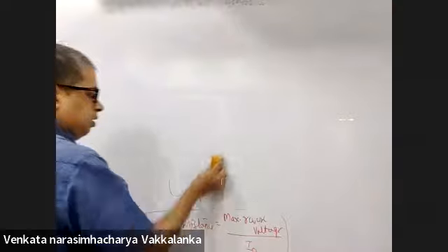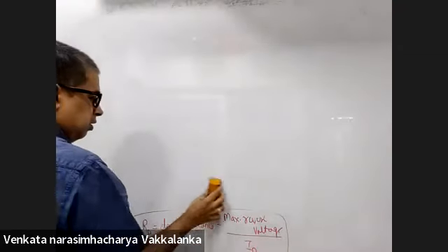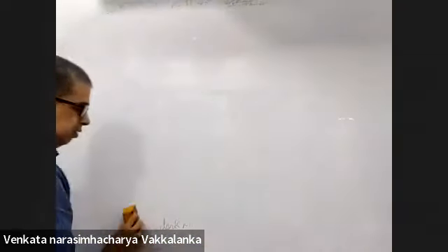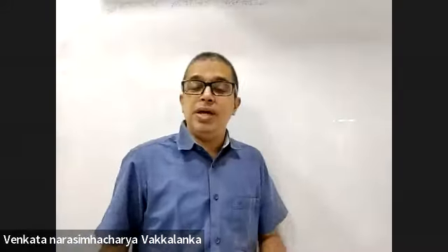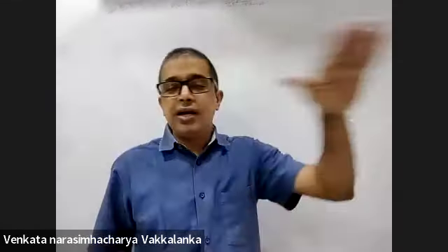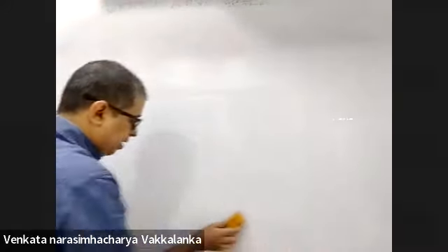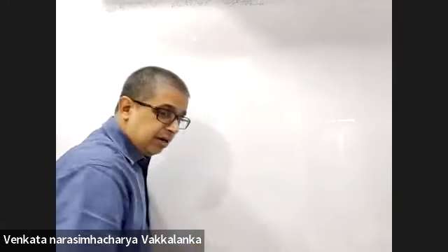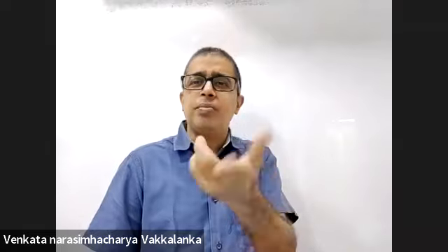So why had we reverse biased it? Even if it was forward biased, we would have got a similar graph of current versus intensity. But with a little bit of forward voltage, it will start conduction, and saturation will be reached very fast. Forward bias we don't want; even in the reverse bias we are having dark current. In forward bias, we'll have abnormally huge dark currents, even when light doesn't fall, with a little bit of 0.6 volts, and it will trigger the circuit.